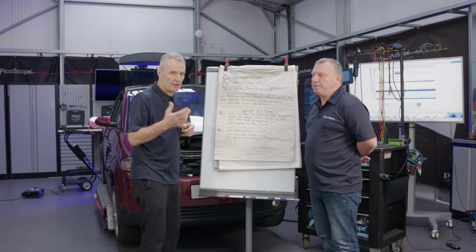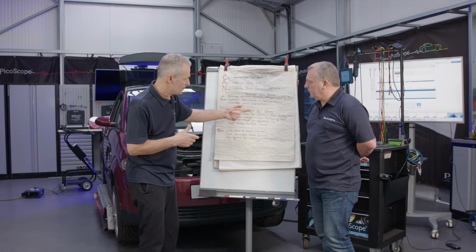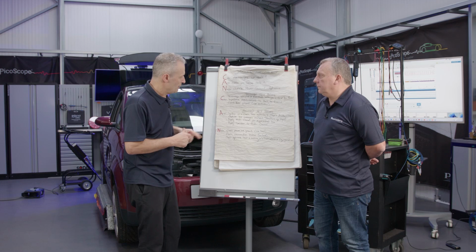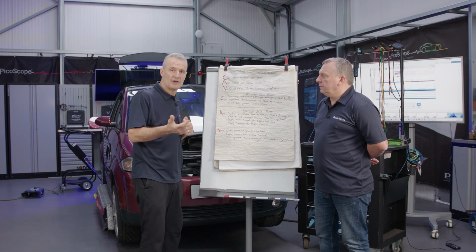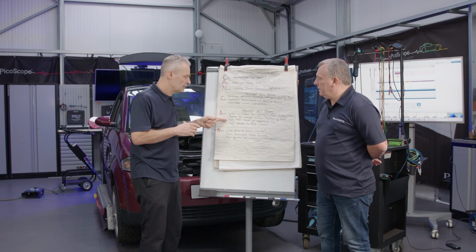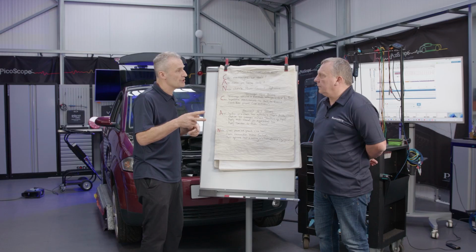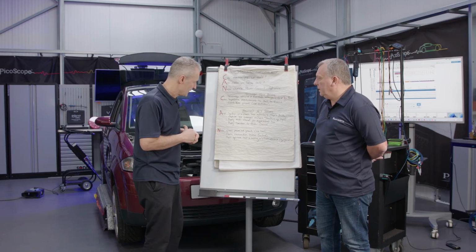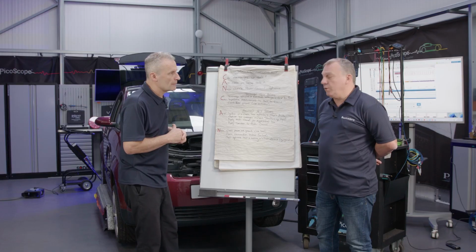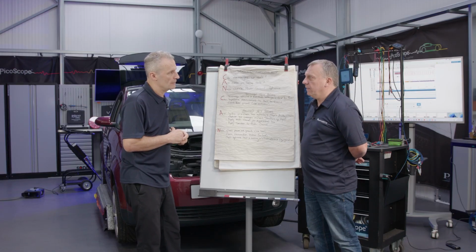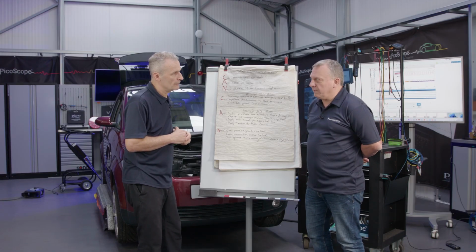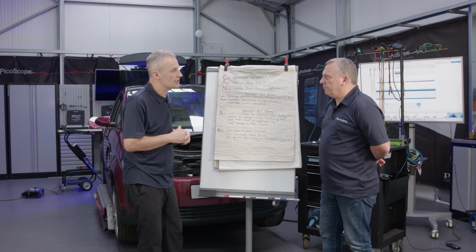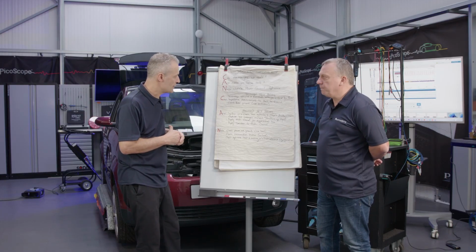We went a bit deeper then with the decoder. Capture messages, check the structure. Apply the math channel. We talked about the differential. Yeah, only relevant really on a twin wire bus. Absolutely. Yeah, if this had been LIN, then no point. But at that point, we're not only sure that messages are being sent, we know they're being sent successfully. Successfully, of course, because of the acknowledged signal. Because of the decoder. Yeah, and the decoder.